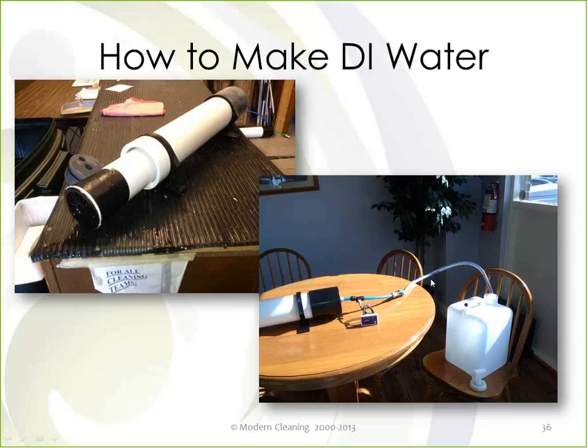The water feeds through the tube, goes through the output tube, and we're putting it in 5-gallon buddy jugs. That way we can seal the jug and store it and fill our quart spray bottles at our convenience. As long as you put it in a jug and seal it, the TDS levels will stay near 0 for long periods of time. I can't tell you for how long. We've done it for several months, and I've seen no shift in the TDS level.